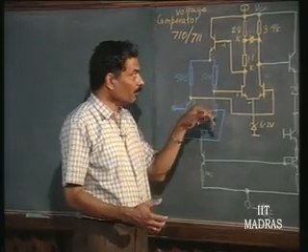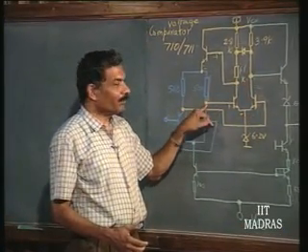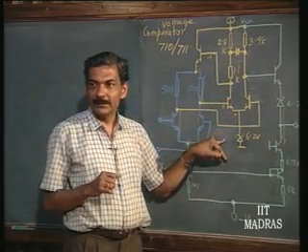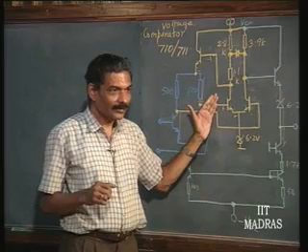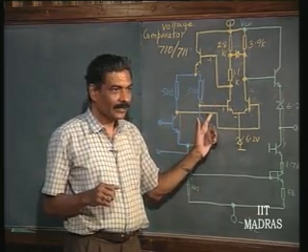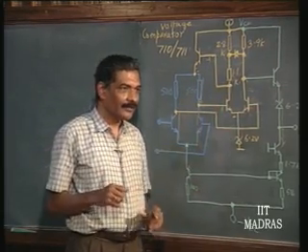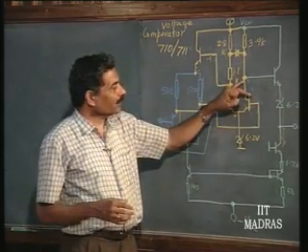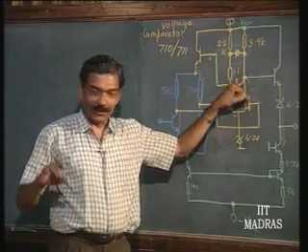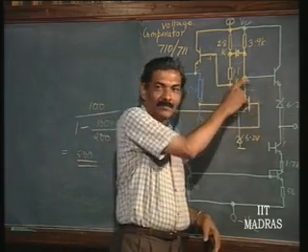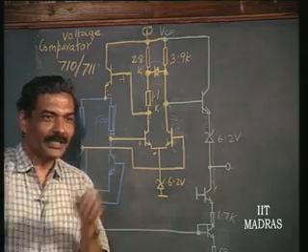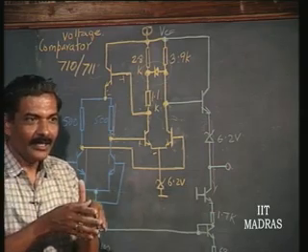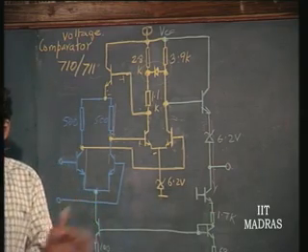If you have to use, then you will put a what? Compensating capacitor between this and this and this. In fact, there are two separate feedback paths here, right? There is an internal feedback here, okay, and here, right? So, it might cause problems, right? Most of the times, the internal feedback itself is sufficient, because please remember, this collector based capacitor is there. We are putting additionally some capacitor to make it dominant, so as to make it work for every gain that you are thinking of.